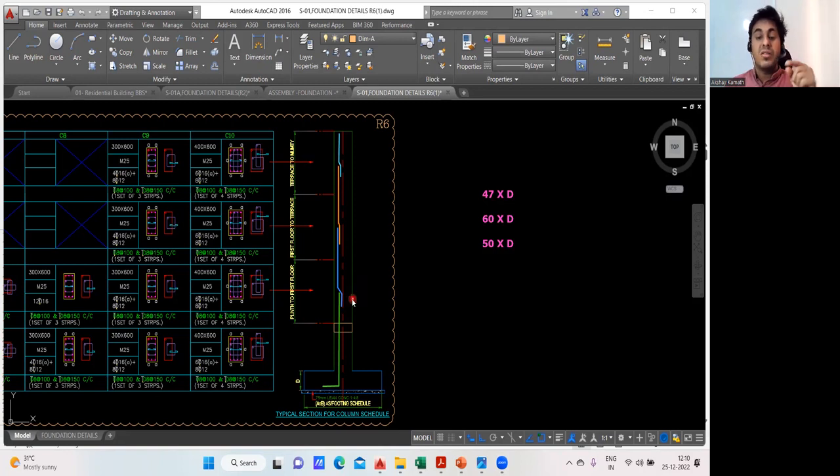Now you may ask me one question. Sir, the total height is this much. One straight 12-meter bar we never give, because your rebar will fall later. So the usual practice is every floor we give one lapping. Once your bar starts from the foundation up to the center of the plinth beam, you give one lapping. Again, you ask me, why does it have to be given in the center only?